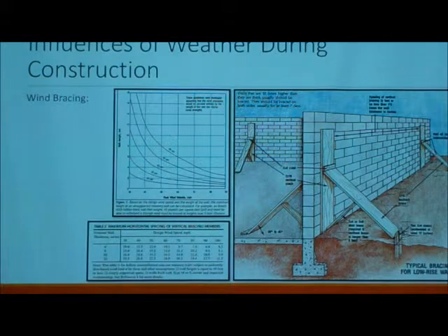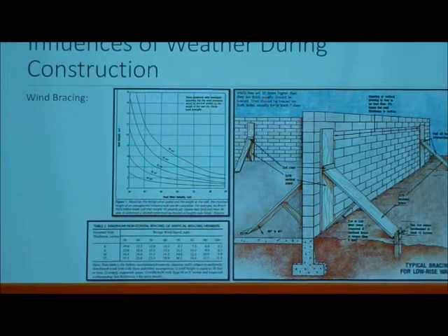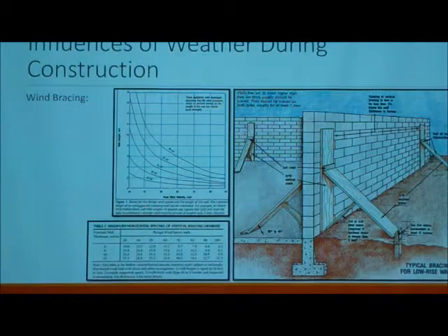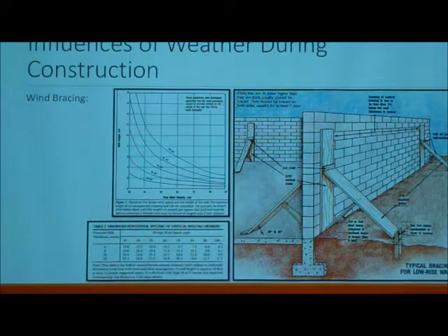Compared to this one down here, you can see that it doesn't have this little kickstand right here. The problem with those is that they would be able to move with the wall instead of creating a moment against the wall. So that's an important detail when you're providing wind bracing details.